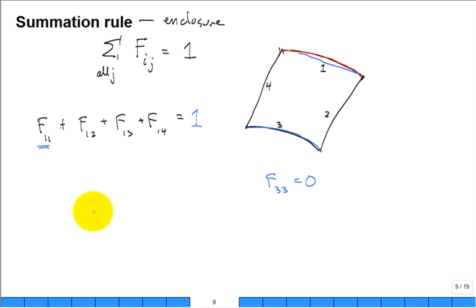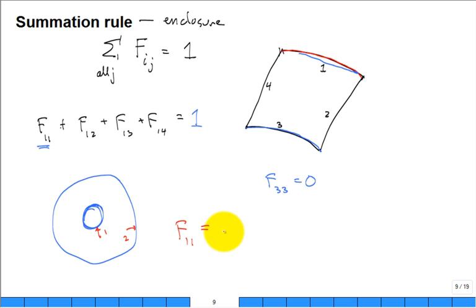Let's do that pipe. 2 surfaces. This is the outer surface of an inner pipe, and this is the inner surface of an outer pipe. And so we're analyzing radiative exchange in the annulus. Again, this is surface 1, and that's surface 2. What is the view factor 1 to 1? Can they leave surface 1 and somehow go in a straight line and hit surface 1? No, they can't. And if I only have a 2-surface enclosure, what is the view factor from 1 to 2? 1. It has to be, by the summation rule, they're going to hit 2.